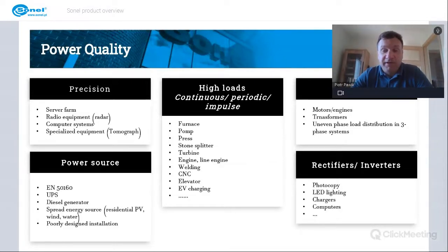Also, we may want to think about electrical vehicle charging. So when we have single-phase AC chargers, and there are a few of them in the parking lot. Say we have 6 chargers, each one single phase. We did everything correctly because we connected 2 of the chargers to each phase. But apparently we have just 2 cars parked and they are on the same phase, so they can cause some unbalance. Of course, the way to prevent this would be to put 3-phase chargers. That would be easier.